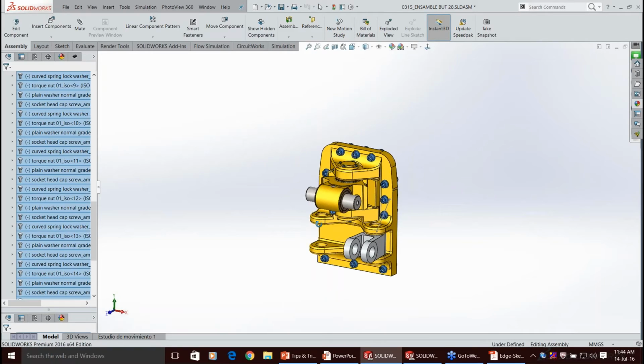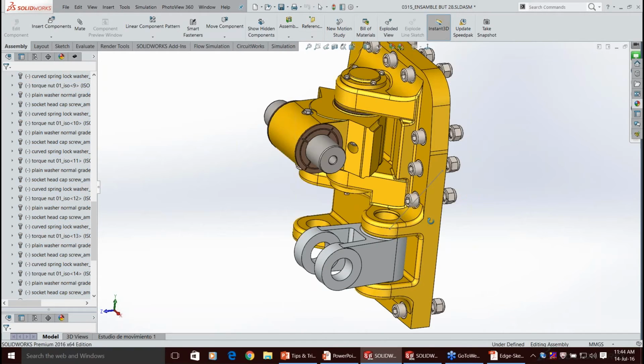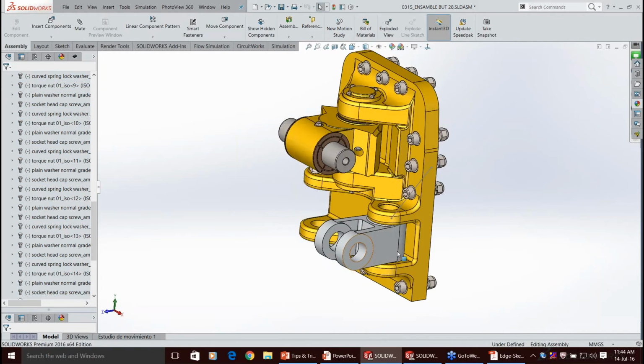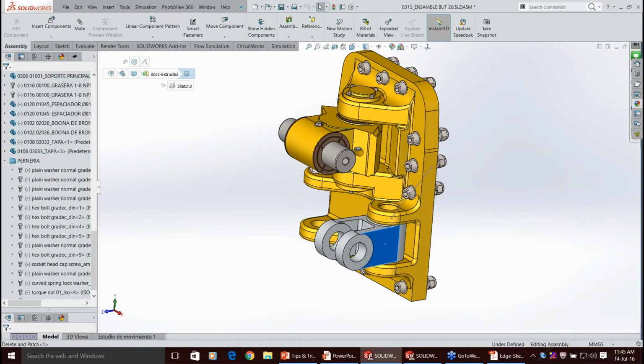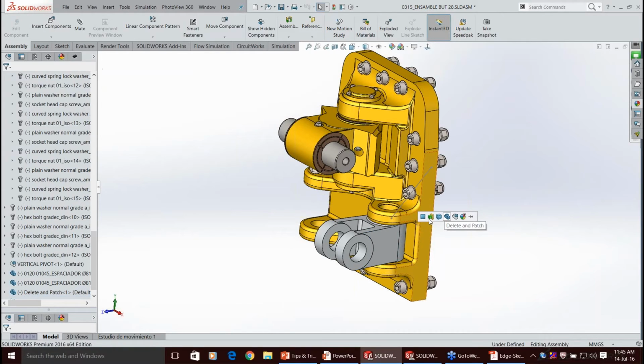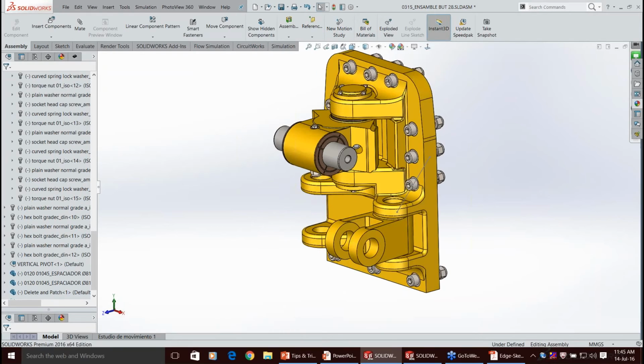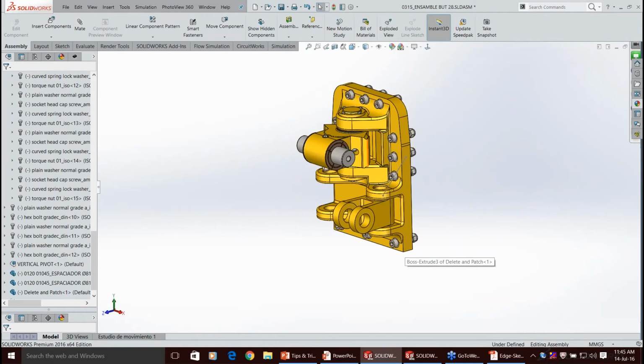And now you can see this knuckle that we created seems to be out of paint, right? We need to paint it. In SolidWorks, you need not again go to appearance and do that. We have an option. I just right click on this, sorry, you can even left click. We have something called copy appearance, right? I just copy this, come on this and say paste appearance. It is asking me for the part or for boss extrude. You have the power to select whichever you want. I say for the entire assembly. You saw that in a matter of just 2 clicks, I painted the entire knuckle in the same color as the assembly, right? So these are some things which will be very useful to you.